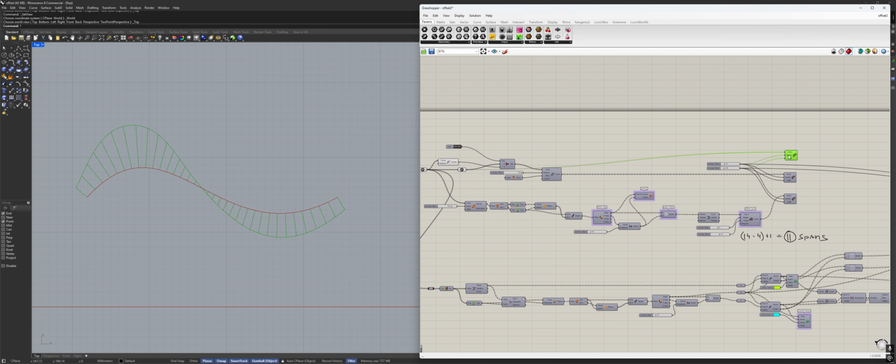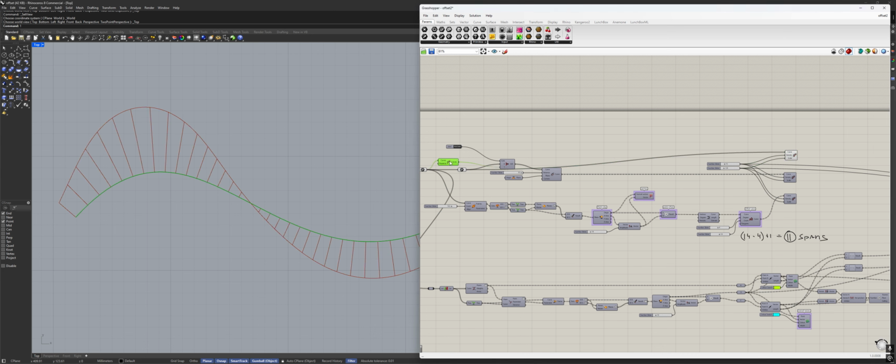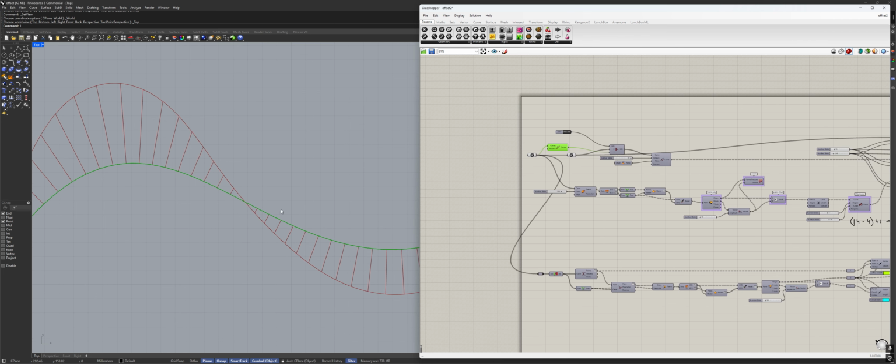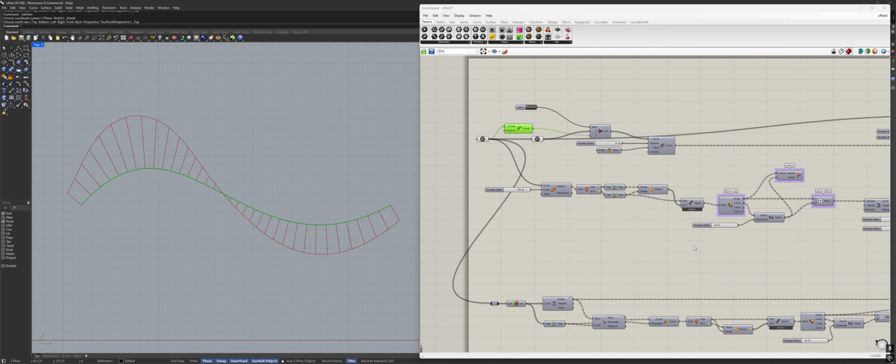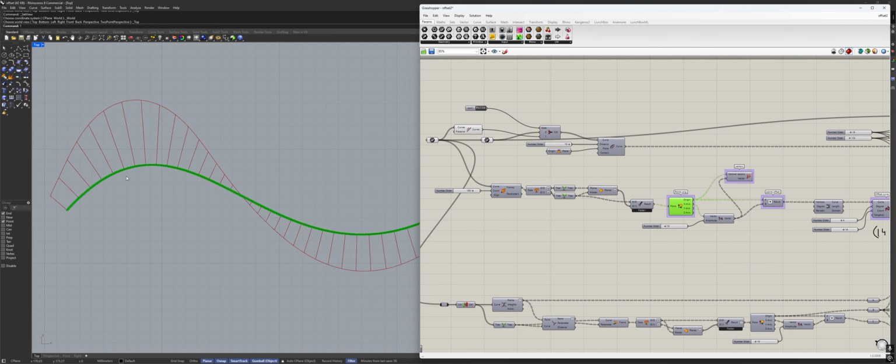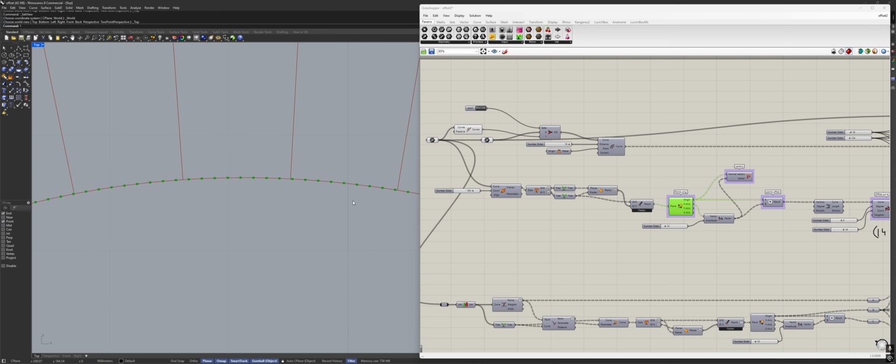And as you're going to see, I have the curvature comb plotted already, and you're going to see it's the same. So this is the same curve. Now, when we're talking about the automatic algorithm in Alias, what it means is that Alias will take an original curve, subdivide it into multiple segments, basically populated with points. Let me just activate the points like this. So now if you zoom in, you're going to see there is a lot of points on this curve. Quite a lot of them.